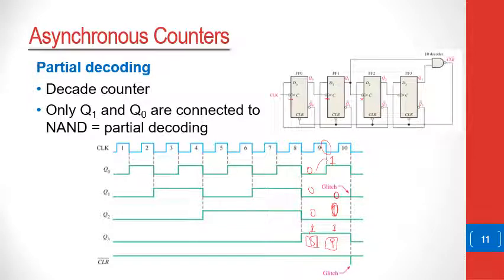what will happen is that in the next state, as you experience another negative edge of the clock, the counter will then attempt to go to 10, which means it will attempt to have for a moment a particular state where it has a 1, 0, and then it will attempt to put up a 1 here, and this will attempt to become a 0.